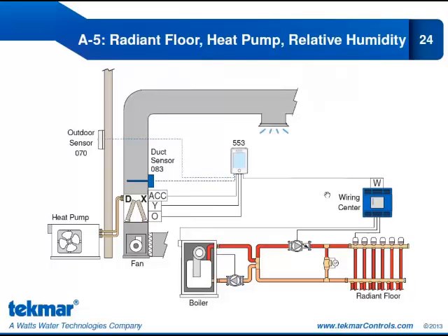Our second stage of heat will be from the heat pump. So our Y is going to the heat pump. And because we're using a heat pump, our GO relay is going to operate the reversing valve. So we have it set to O here in the diagram.